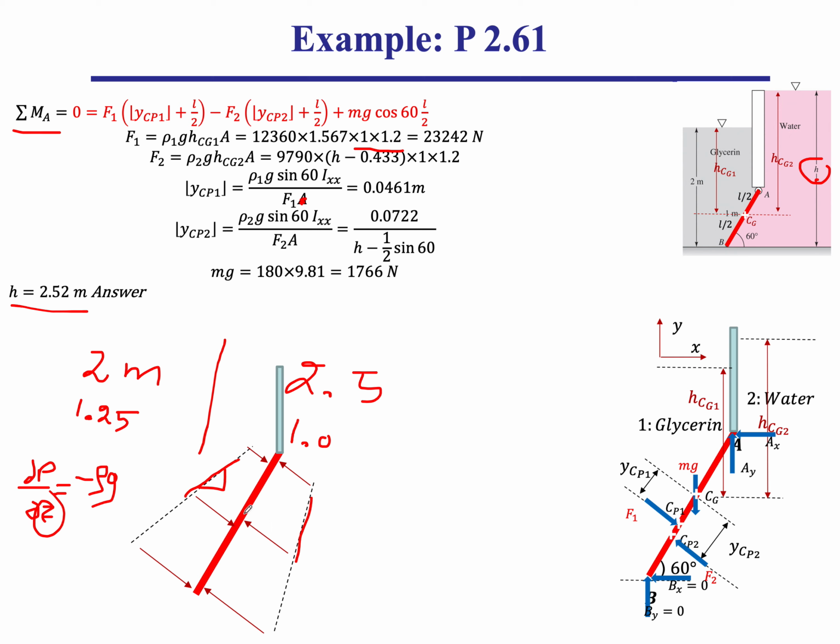So just make sure you understand the gist of this whole thing is that you have pressure distributions on both sides, and due to this linear pressure distribution, you're going to get the net force acting further down than halfway on a uniform depth into the page of the object. So that's the YCP1 and YCP2, the centers of pressure. Okay, we can do one more problem here, and it would be a problem on the Spar buoy.